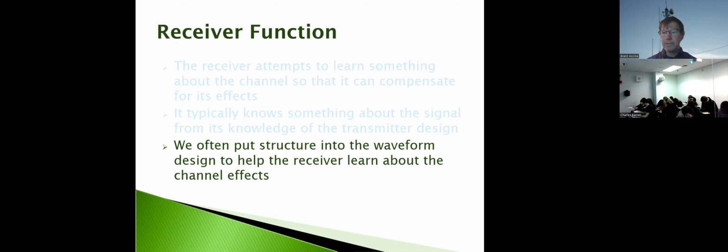I'm not going to test you on this, but I think it's useful to have a good context of this, right? So there are some well-known sequences at the beginning of that frame, and then the receiver can look for those and synchronize its timing associated with that, right? So it knows when a frame is beginning. And then there are also what we call pilot tones or reference signals.